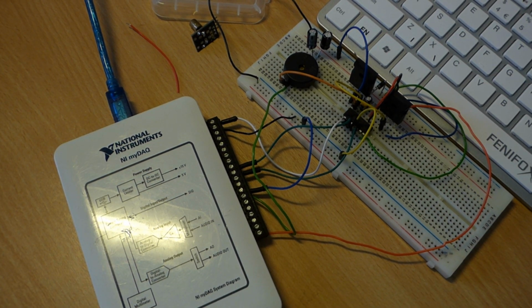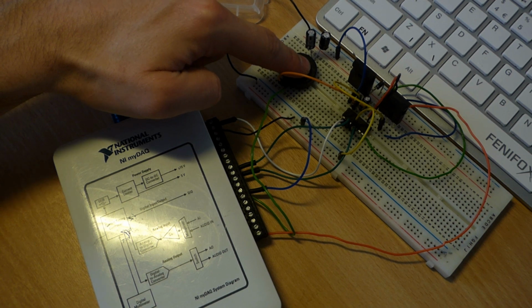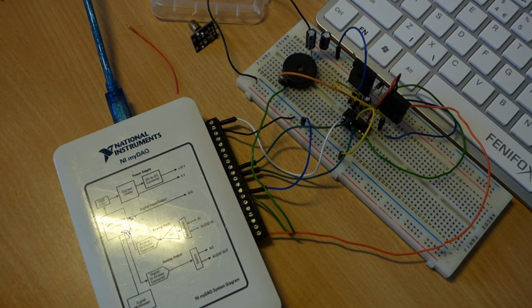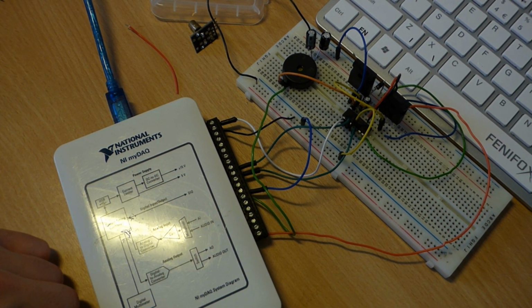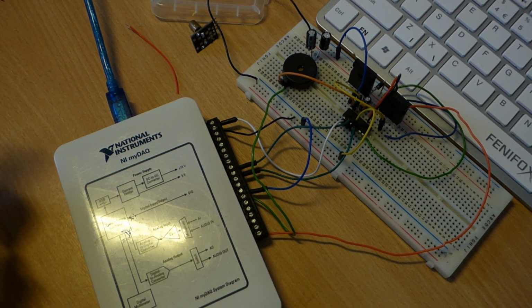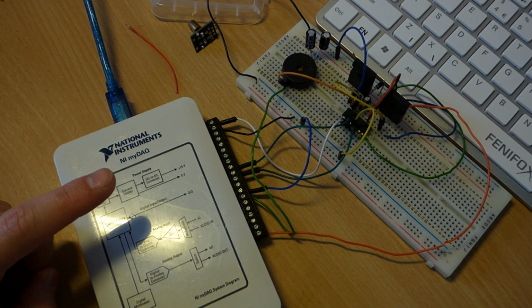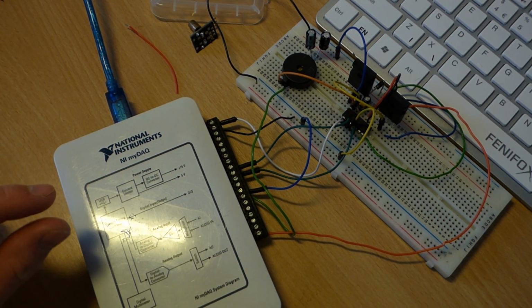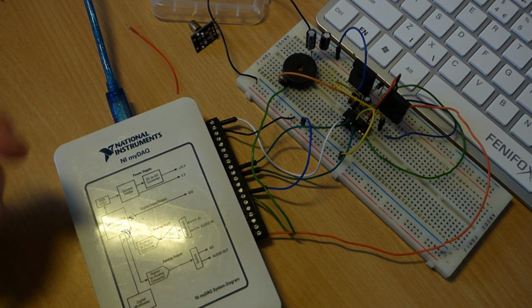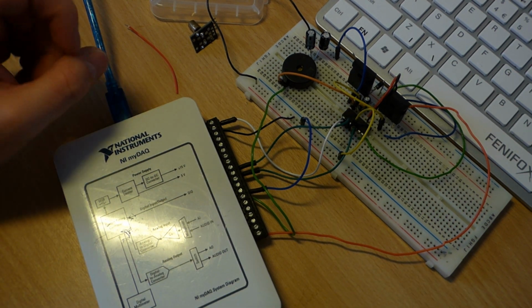And here it is working. It's a rather annoying noise, but that's the buzzer switching at approximately 1 kilohertz. Sorry, that's the maximum that the myDAQ can do. If you're interested, it uses the PC's millisecond counter, and so 1 millisecond is the smallest resolution that you can get. So the reciprocal of 1 millisecond is 1 kilohertz.